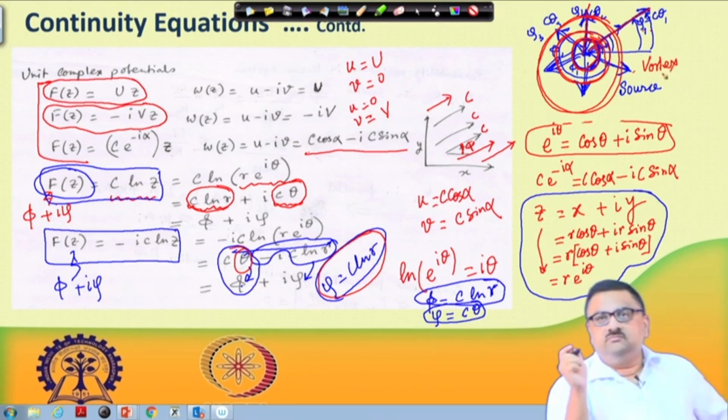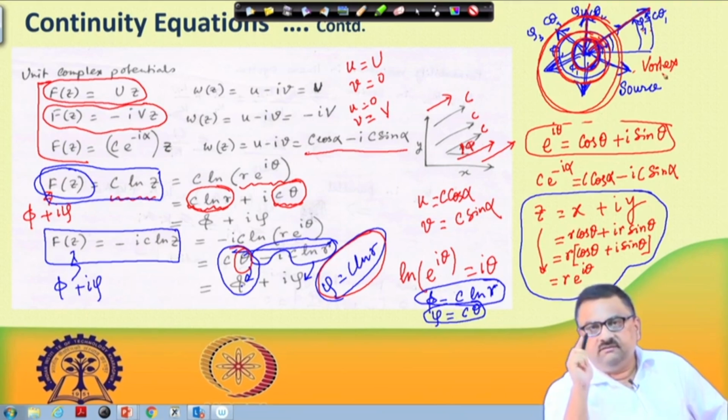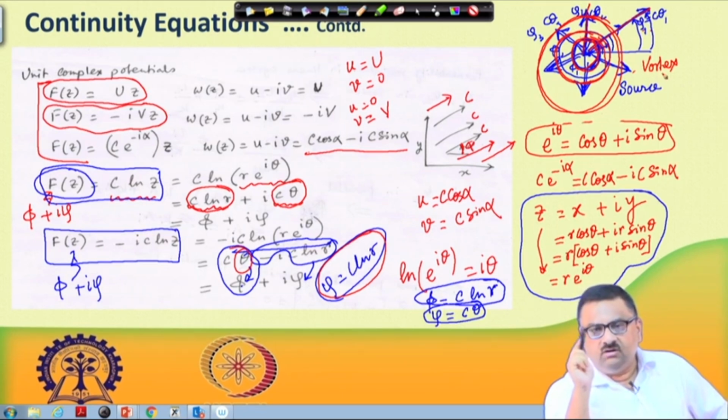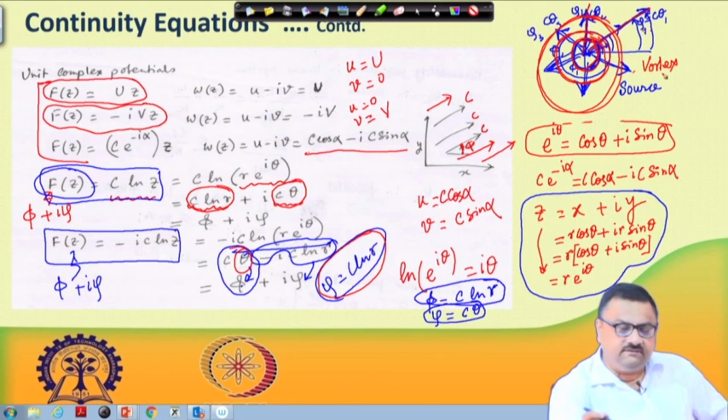Of course, when it comes to vortex, people generally talk about free vortex or forced vortex. We are referring to free vortex. There is no viscosity involved here, no layer is sliding against the other. Generally, near the core of a vortex, it is called forced vortex, and there viscosity plays a role, but away from the center of the vortex one can get a free vortex where the flow is in circular streamlines. So, we are referring to free vortex. So, this is a vortex.